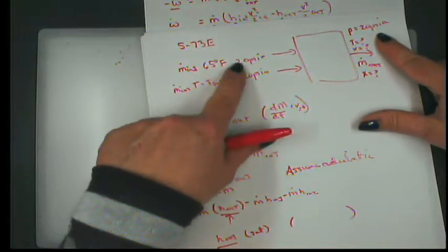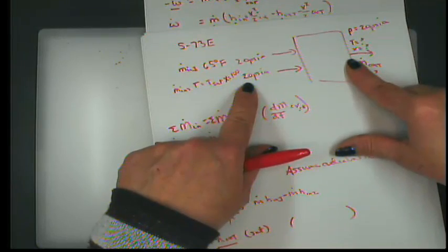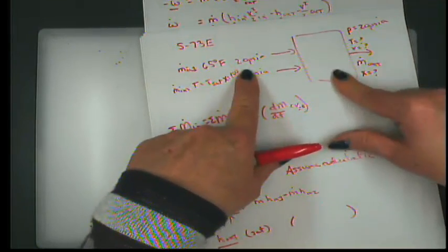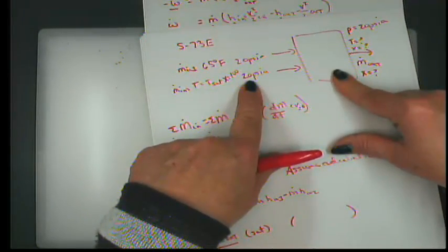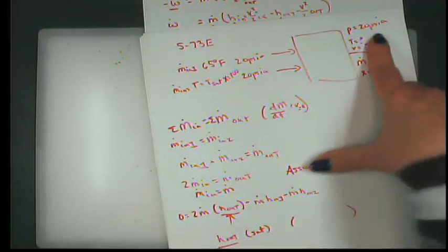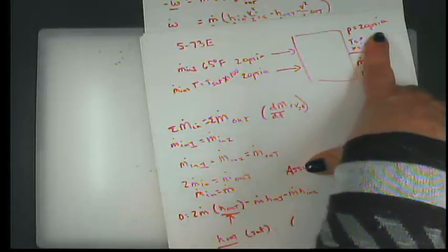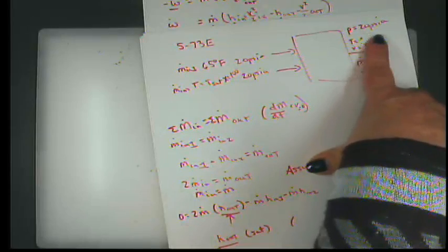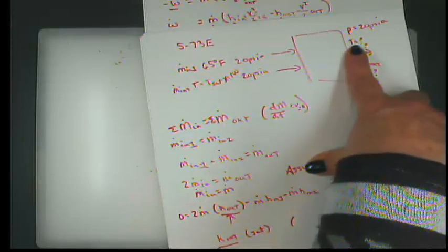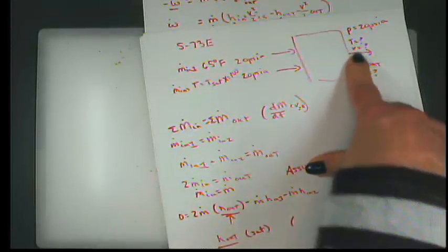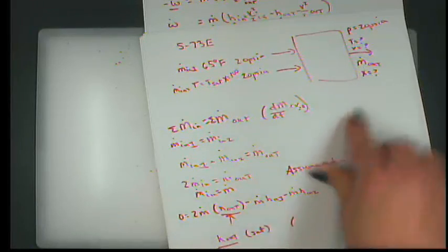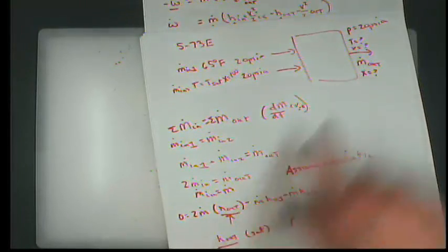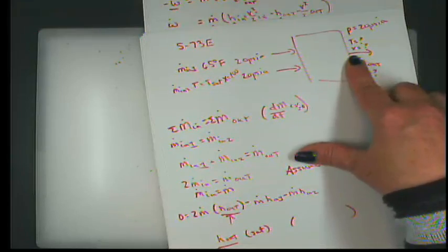The reason is because there's nowhere on this exit, it's not going to reach equilibrium in the system until it reaches 20 psia, is it? Because both of these streams are at 20. So over here, you can make the assumption, fairly good assumption, that the pressure is going to be 20, and find out what the T is. You actually know then what T is because it's saturated, and then you can use that just to find that value of H here and solve for X.